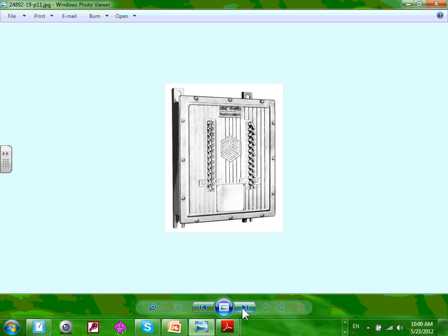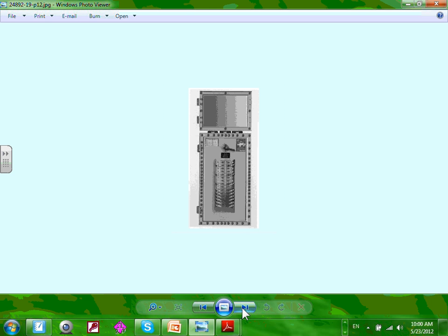So here's a panel, explosion proof panel. If you guys look at page 292, it says 19-11. This is good for class 1 group C, D, class 2 group E, F, and G, and class 3. Manufacturers are smarter than us. They make a material that fits a lot of these specifications. Instead of splitting hairs, here's one that's good for all, C and D.